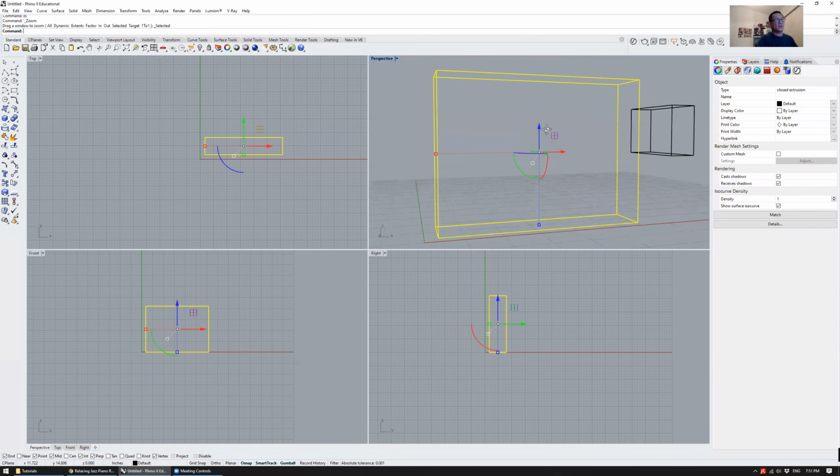You'll see these planes in place there. These are there to say, what if I only wanted to constrain my movement to the XZ plane, so the red and the blue direction, so it's only moving in that plane. This is similar to if I had gone out to one of these views and said, hey, I'm just going to move it around in the XY plane, shoving it around horizontally.